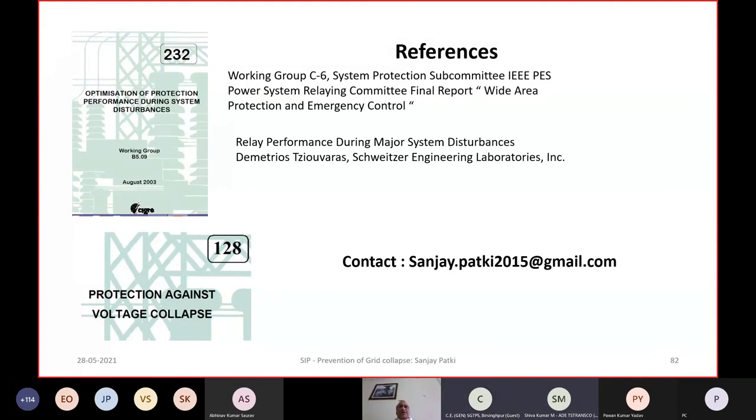See, the sympathetic inrush will be an unbalanced condition, and unbalanced current will flow like a zero sequence current in the earth fault circuits. So you have to increase the pickup of the earth fault circuit. There is also now, in numerical earth fault relays, the harmonic restraint feature, the second harmonic restraint feature. Normally, this is not known to many people, that overcurrent earth fault can also be provided with second harmonic restraint. So if you use the second harmonic restraint, you can have a sensitive earth fault protection also. So please use second harmonic restraint in the earth fault.